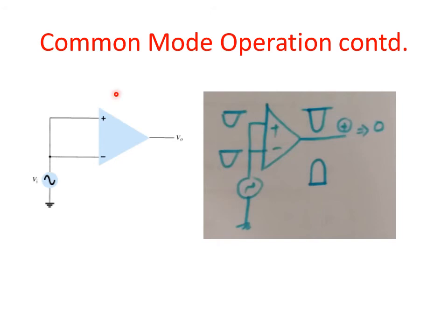Now you see here again the circuit is the same. This is the supply, but from the supply the negative peak is basically coming as the input. What will happen? The positive terminal will amplify it without changing the polarity. The negative terminal will not only amplify, but it will also invert the polarity.